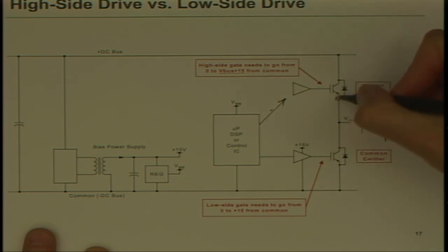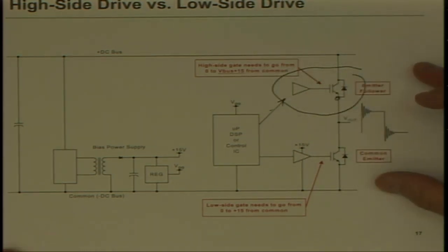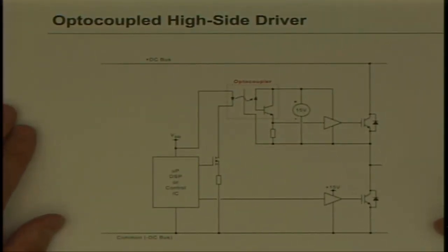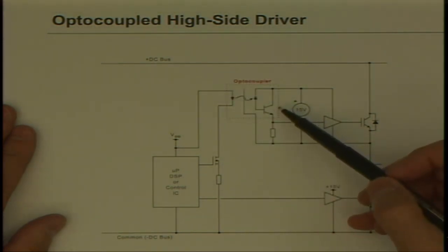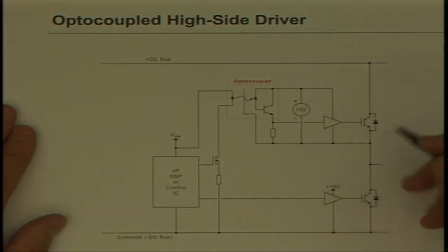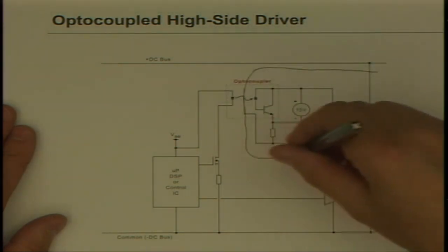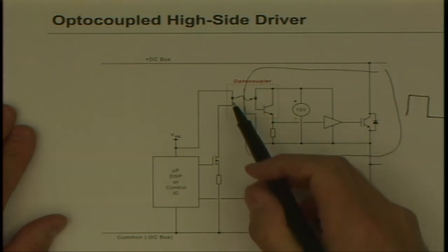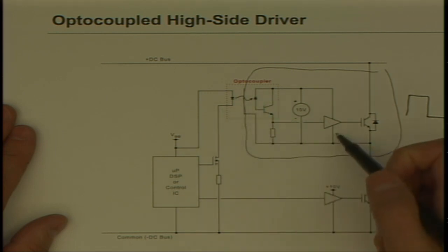that's basically the emitter here. So is the gate, right? This whole thing is moving up and down. So one way to do that is to isolate using some sort of optocoupler, which is commonly used. So that allows this whole node to float up and down as you switch the output, and you communicate with light, essentially photons, to tell this when to turn on and off.